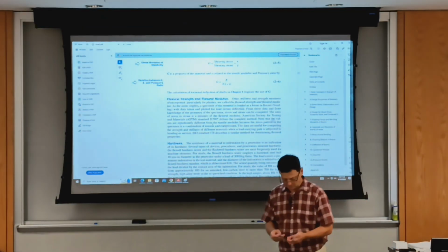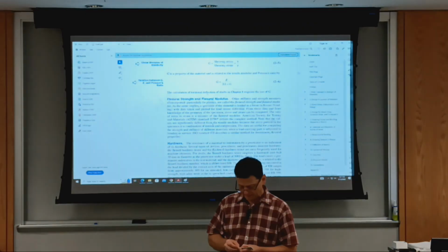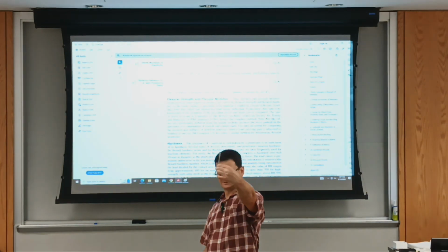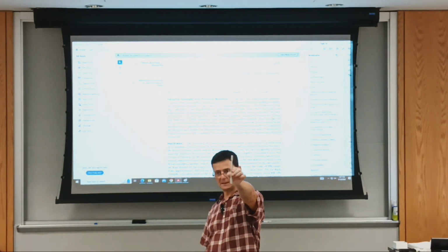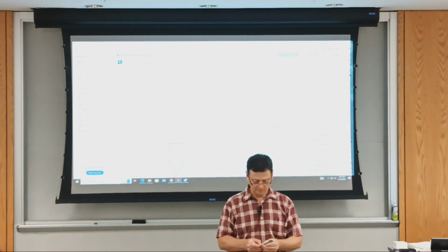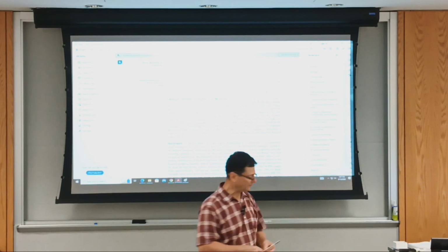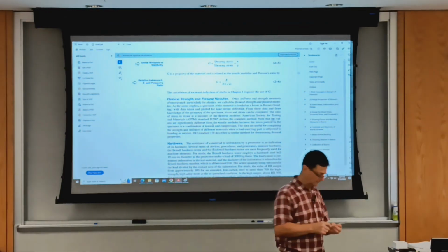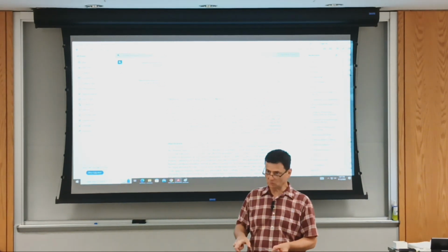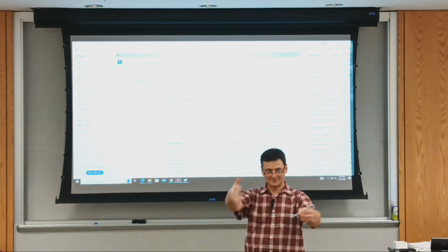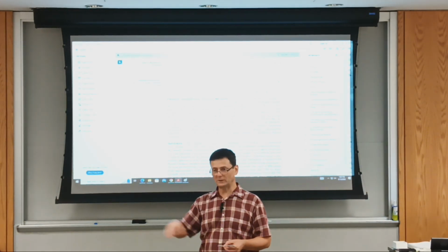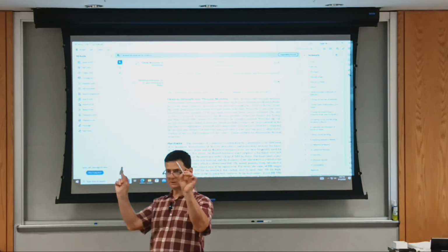I mentioned last time Steel Dynamics here in Sinton, and they have a lab where they cut standard-size specimens for sheet metal, and they test them, and they affix a bulletin to the batch if there's a requirement. Usually it is, we want this type of rolled sheet metal with these properties, and they run the test longitudinal, transverse, at 45 degrees to the direction of rolling, because rolled sheet metal is not fully isotropic. I think you looked at this one, right? Okay.